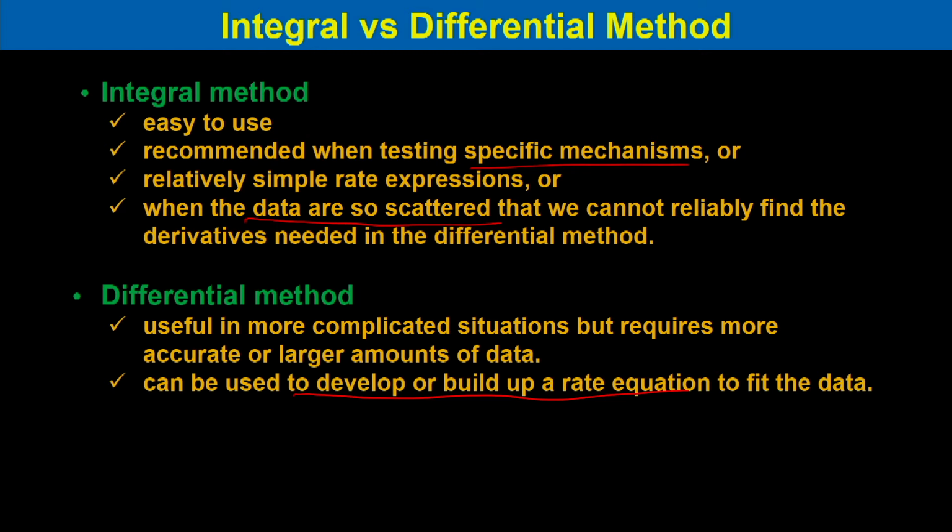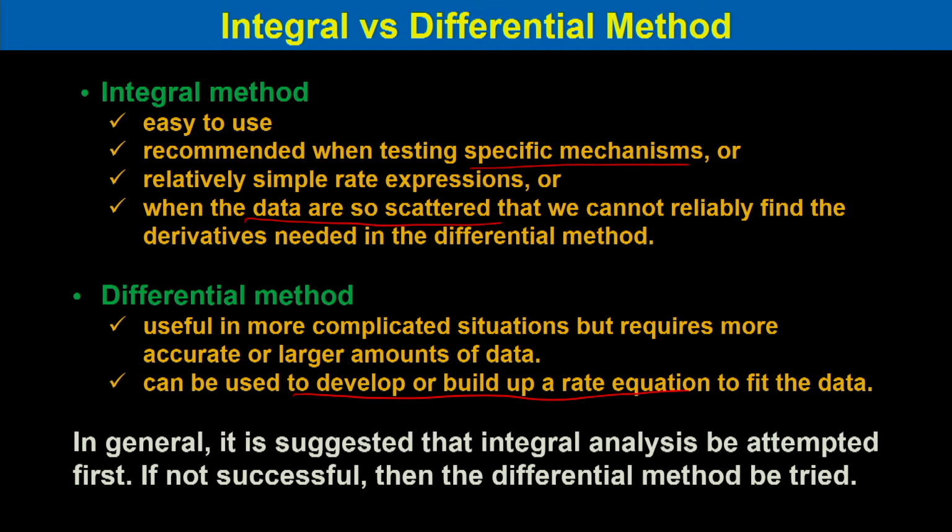Whereas in the integral method we have to guess the rate equation, in the differential method we can develop the rate equation. As general practice among these two methods, it is suggested that the integral method of analysis be attempted first. If the integral method is not successful, then we use the differential method. So, this is the general procedure to be followed to obtain any rate expression.